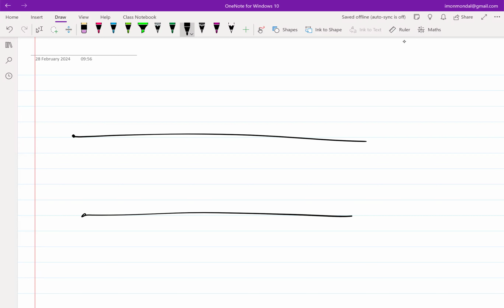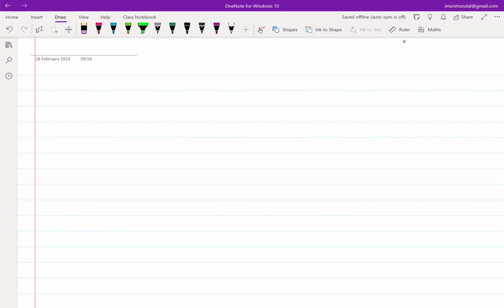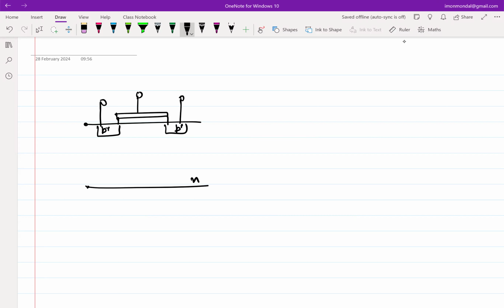So let's say I have a PMOSFET device where the substrate is N-type. I put an oxide, I put a metal gate, and here we put P plus layers. This becomes the gate. Let's say this is the source, this is the drain. Again, just a quick revision. What are we doing? We are putting a battery between the gate and the source, and we are also putting a battery between the drain and the source.